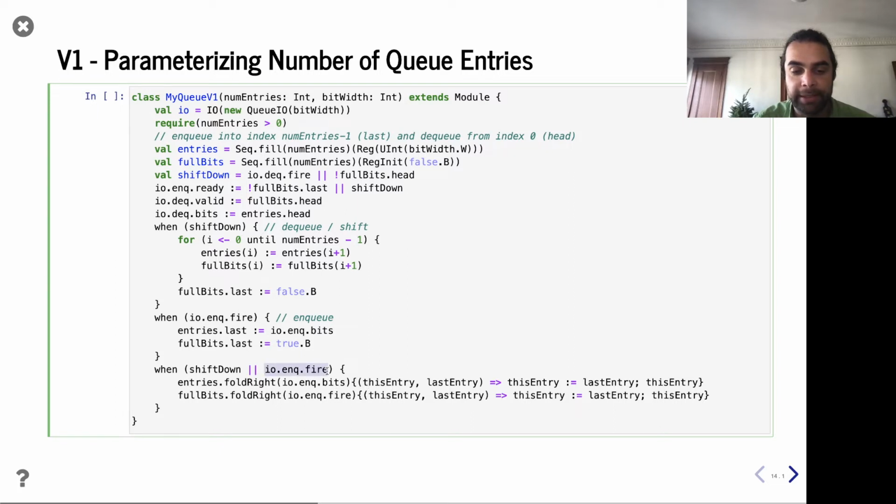But now what about the case when we're shifting down? Well, when we're shifting down, we don't touch that. But as we said a second ago, if we're shifting down and we're not NQing, we actually don't really care about the status of those bits, because those bits only matter if that entry is marked as full, right? If it's empty, we don't care. So actually, we are going to be pulling bits into the register, but we don't care what they are. And the reason why is look at the full-empty bits.